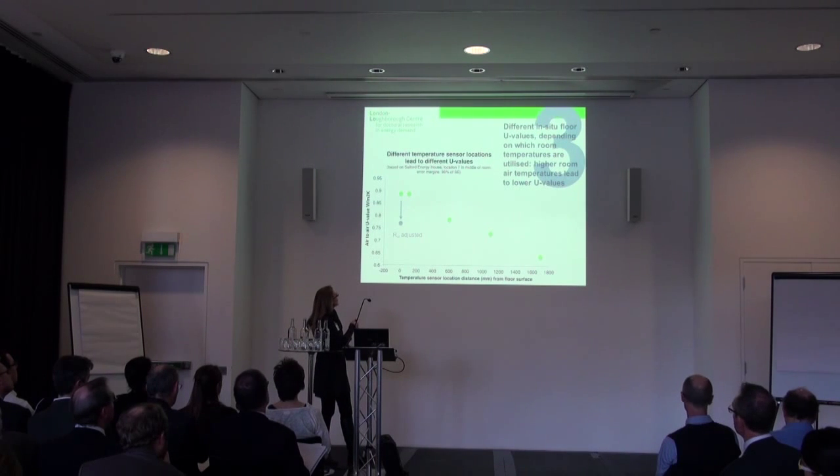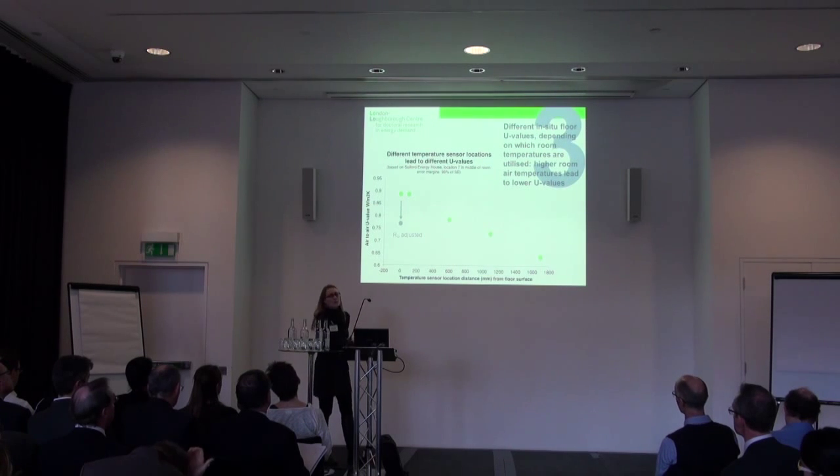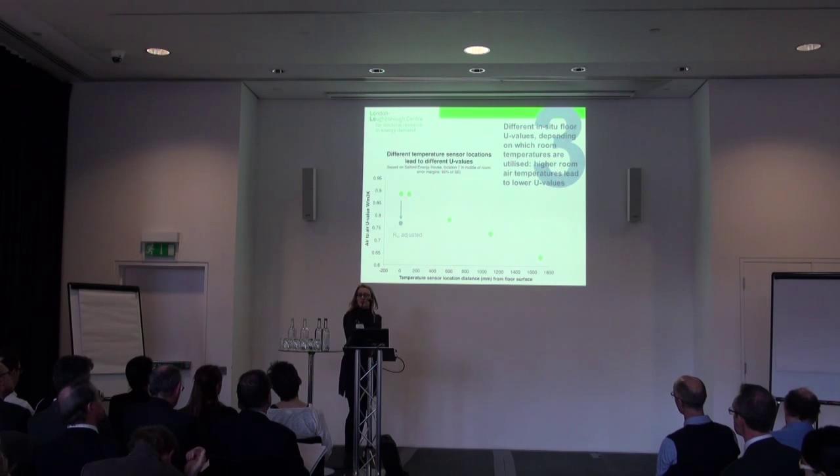Just one final note: if you take the floor surface temperature, then you need to adjust that as well with the surface resistance, which again drops your U value.